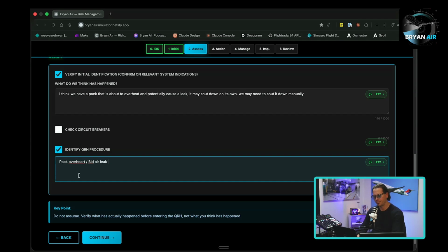Depending on your aircraft type, it'll be different for each type, of course, but again, use your own aircraft type, and if you have a QRH available, then at least you can have a look what QRH procedures are available to me in this situation, which really helps because it gets you to actually page through and use the QRH, and we see that so much where there's not enough familiarity with the QRH because you're not using it every day, so it becomes this book that you pull out once in a blue moon, and you're not familiar with it.